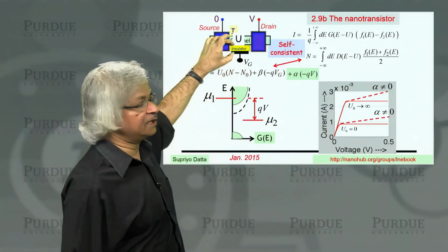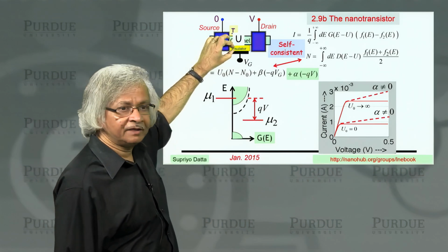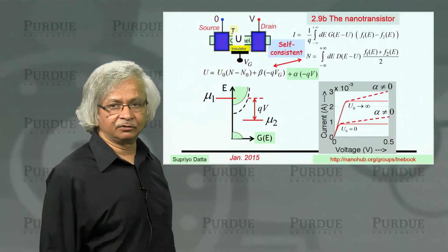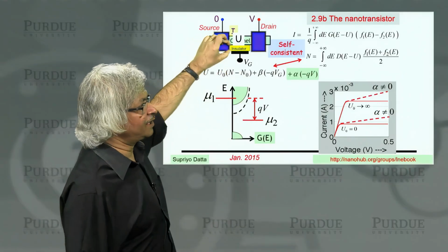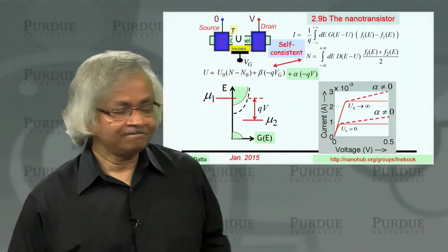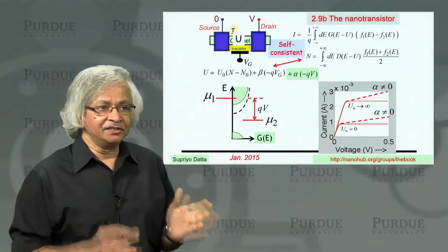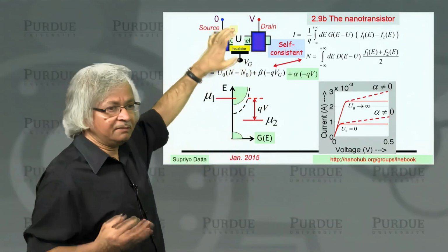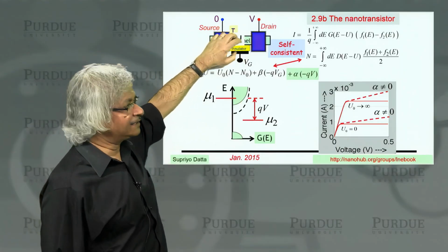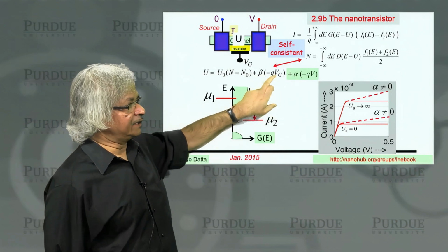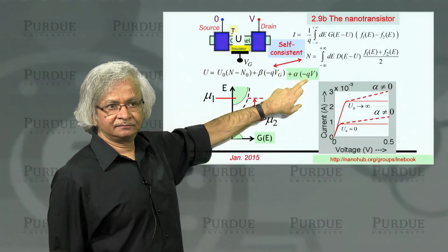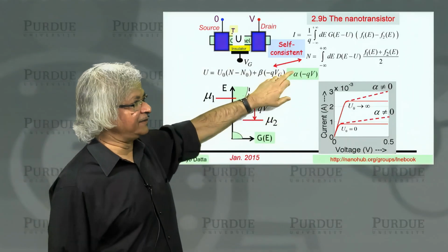And that, of course, is extremely hard, because once it's thin, it also means there will be more and more leakage currents as electrons tunnel through that insulator. Not to mention that it's very hard to control something to 10 atoms across billions of devices. So that really is the major engineering challenge in terms of how to make billions of these nanotransistors work: how you can make the insulator thin enough that the gate controls the channel potential much better than the drain controls it. So that's kind of what determines a well-designed transistor.